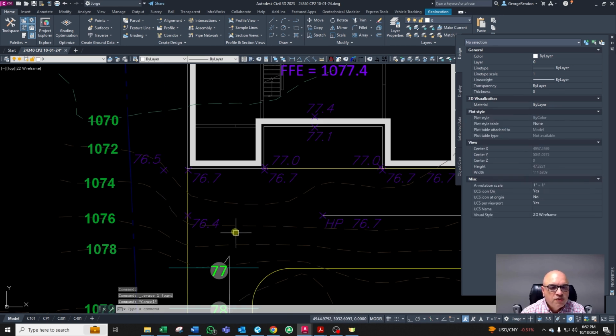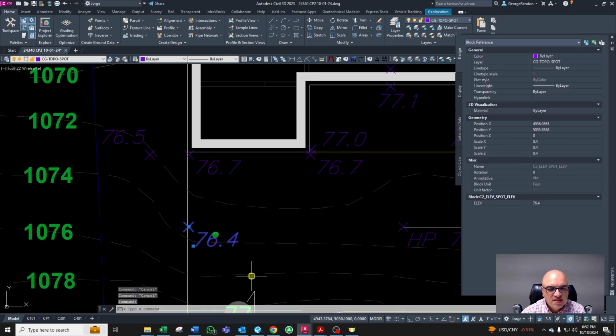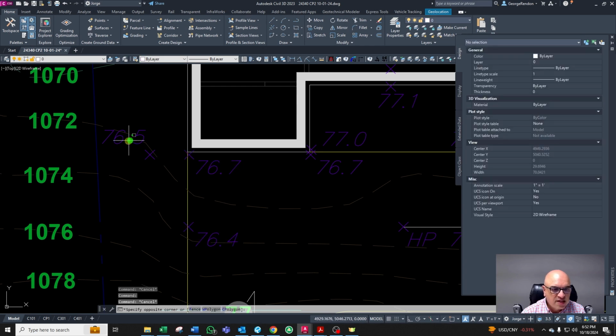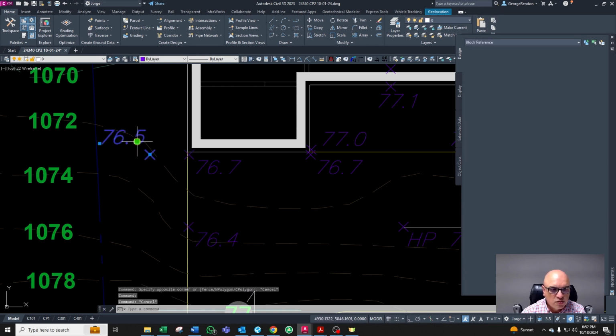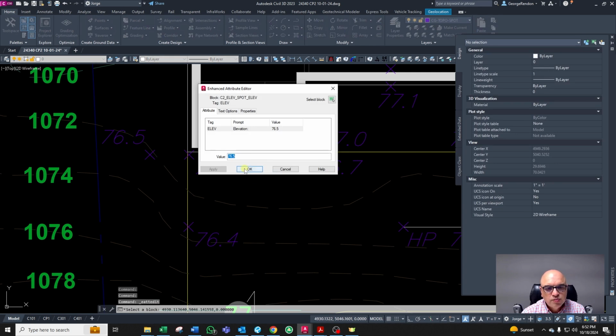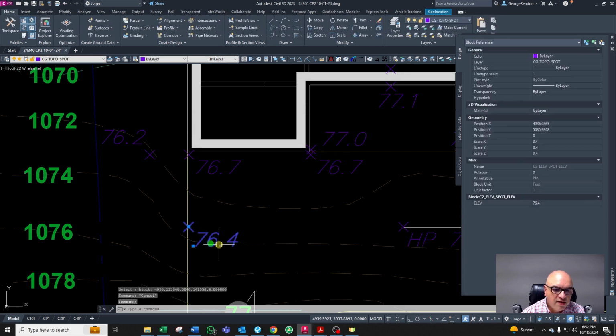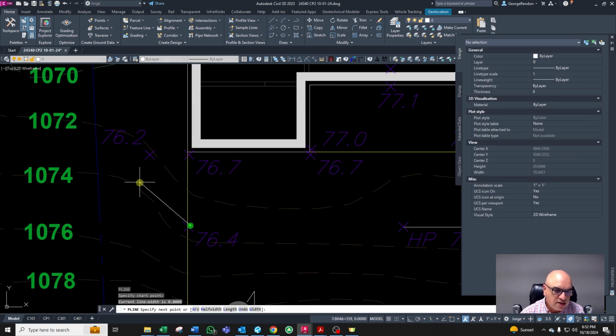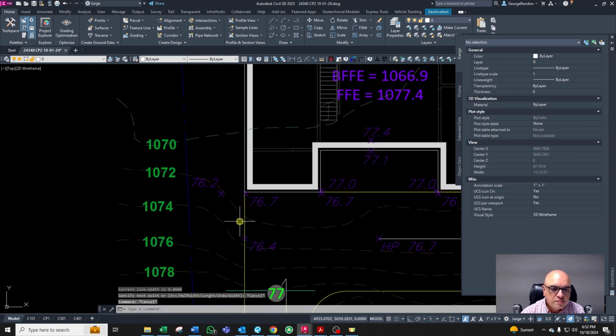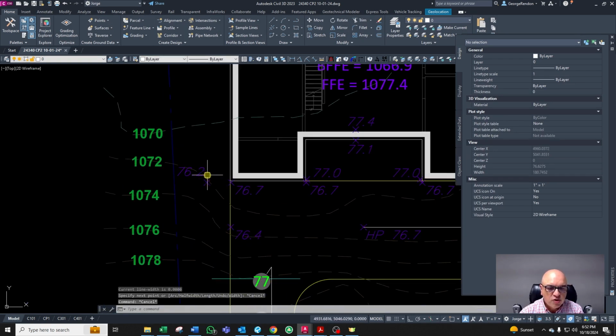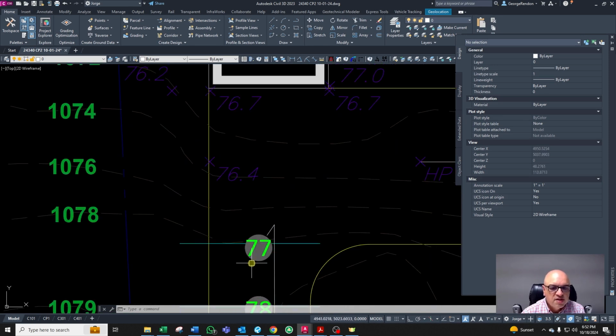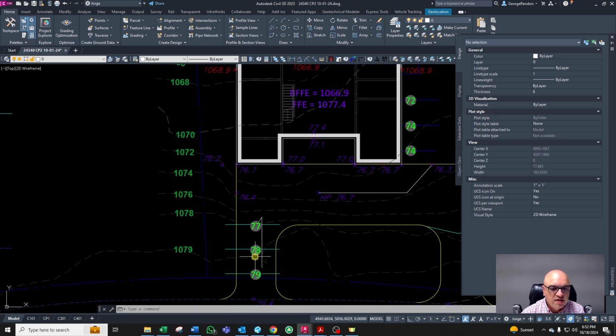But we also got this 76.4, and we need to drain this water, and this is higher than this one. So basically, we need to come 2.2 below that elevation, so this water can actually drain in that direction. If that is 76.2 or lower, we can have lower, but this is 77, and this is 78.